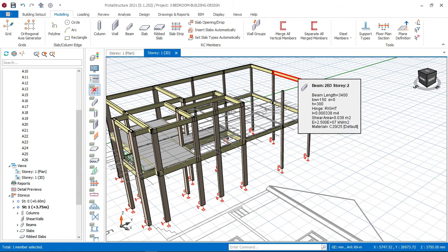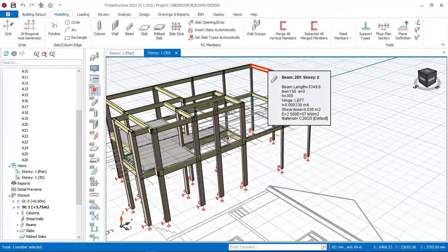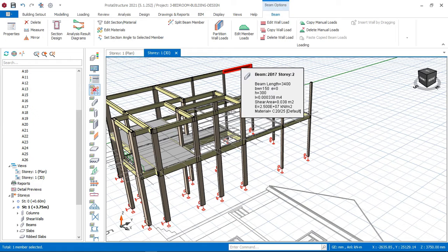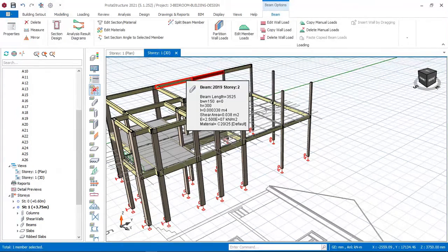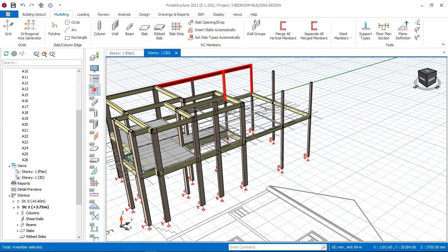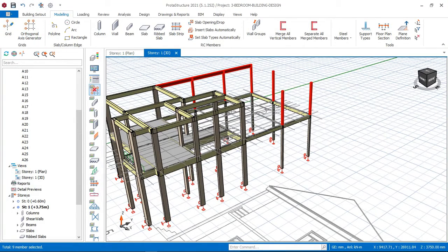It stops directly at this very place. So just take off all these beams right now and the columns that are coming on this very area. So we'll take off this. Let me just hold my control key and select them automatically, and then do the same here, and then here does not go. So click on this, and the columns also are going down. So just take them off, take this off, take this off, and take this off also, and then we will